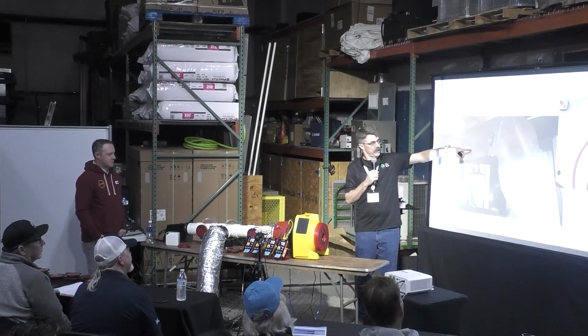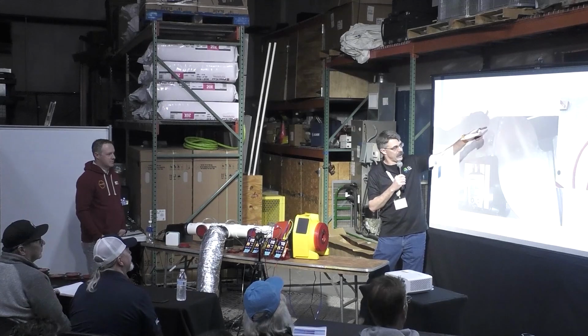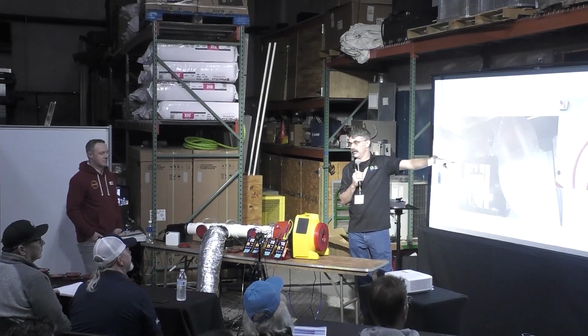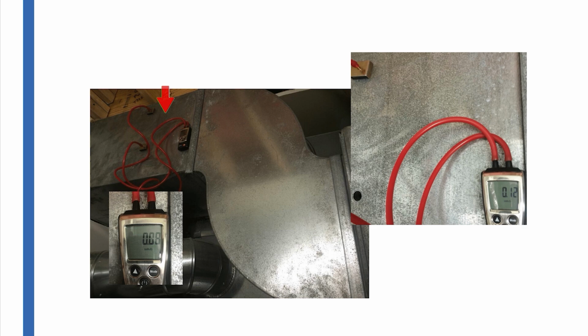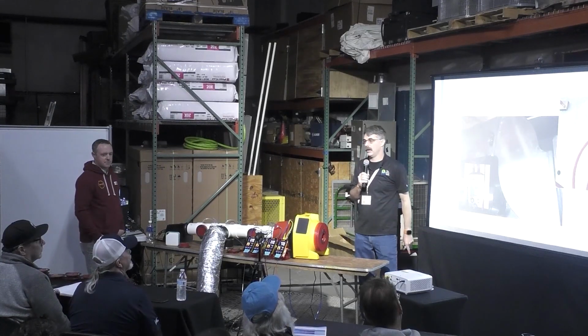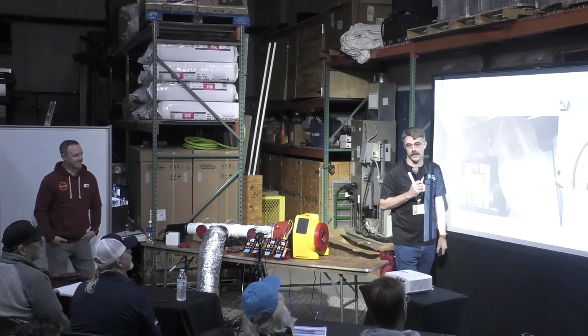But this was turbulence. Because that was trying to make that sharp turn one right after the other, there's a lot of turbulence in the lower half of that duct, and I couldn't get an accurate reading. This was my first hole that I put in here, and I actually drilled this one second up higher to be able to prove where the turbulence was happening in there and say, hey, this is a big problem, why we have airflow issues in the system.